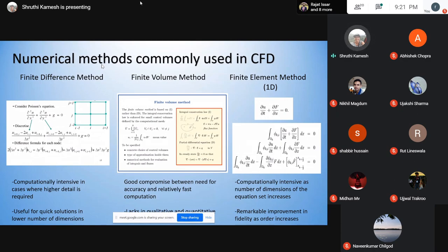Now, another thing with finite difference is that when you refine the mesh, which is when you reduce your delta x or delta y in each direction, your flow would become even more accurate, because you're introducing more points and more elements on which you solve your equations. So you get more detail, right? That's what it means when you say your solution has become much more accurate.